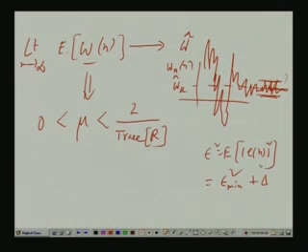But when the filter weights are not the optimal ones, as in the LMS algorithm, the filter weight is not converging on the optimal value directly, only its DC value, average value, expected value converges. So the error variance will not be the epsilon mean square, because we are not using the optimal Wiener filter values for all indices as n tends to infinity. It is only fluctuating around the optimal filter. Therefore, total epsilon square will be not just epsilon mean square, but some extra positive quantity delta will be there. This is called excess mean square error.